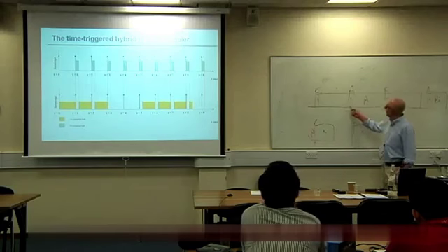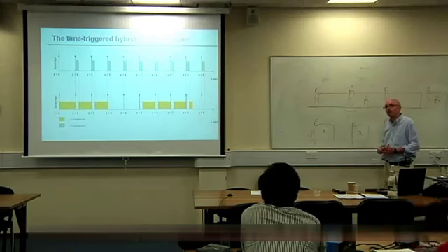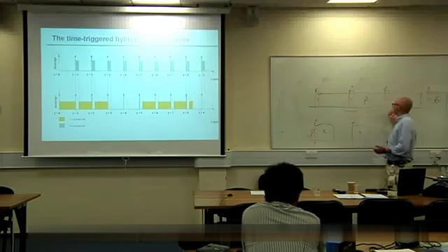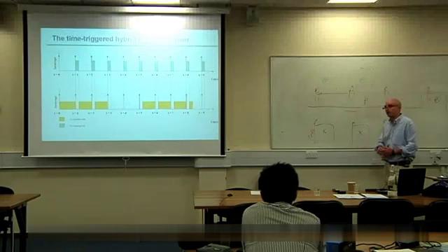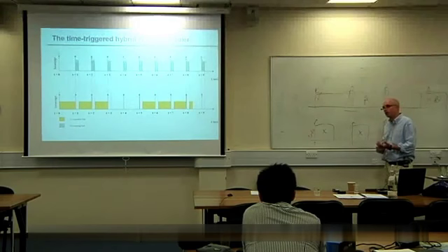What about the jitter here? You're somewhere in a function somewhere. So we know here we're almost certainly in a different state each time. We know that we've got to complete the current instruction that's running before we can service the interrupt.